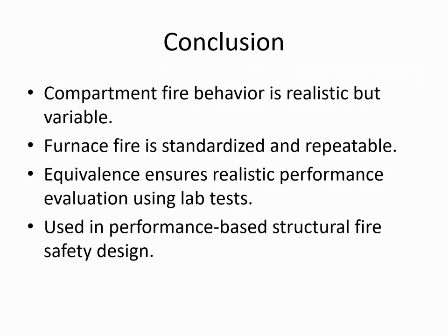In conclusion, the component fire shows realistic and unpredictable temperature behavior, whereas furnace fire offers a controlled standard method for testing structural elements. Fire severity equivalence bridges the gap, ensuring that performance-based fire design can rely on accurate and meaningful testing. Thank you.